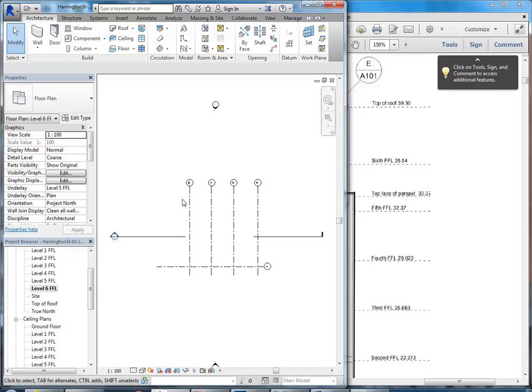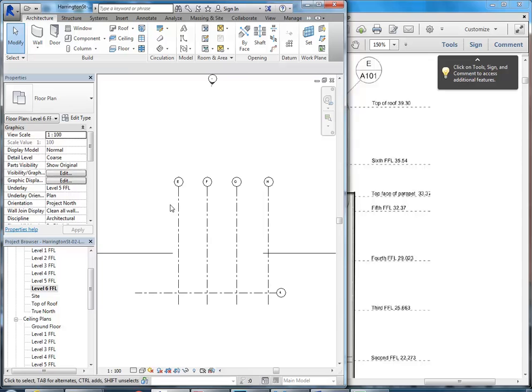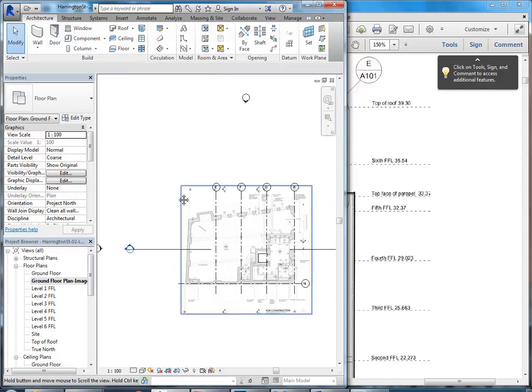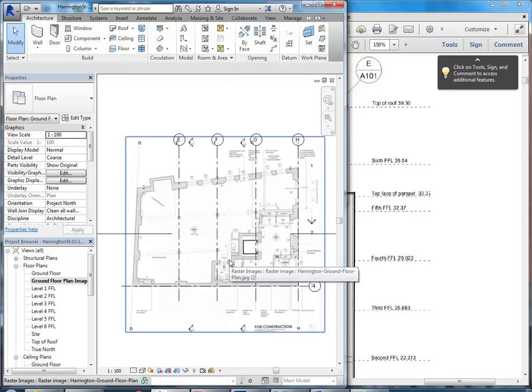So that's okay if you want to adjust existing grid lines and they're visible in an elevation view. You can easily adjust them. But what about those grids that were at a funny angle? There's no easy way of adjusting those unless you make a view at the same angle where you can see them. And that's a lot of extra work, and I think it's actually more work than just remaking the grids. So that's what I'm going to do.